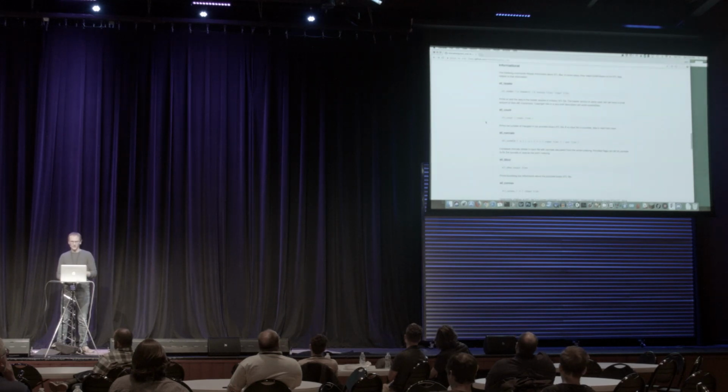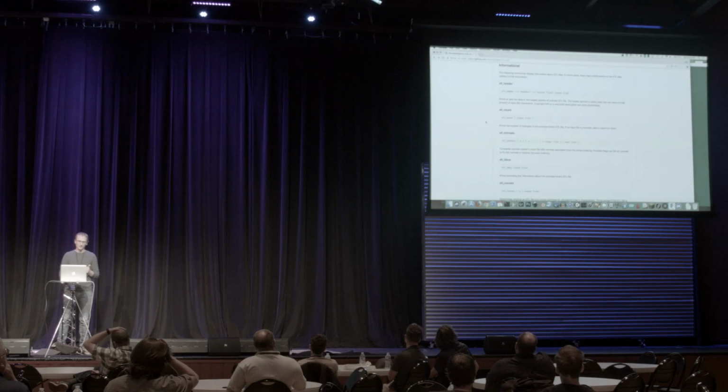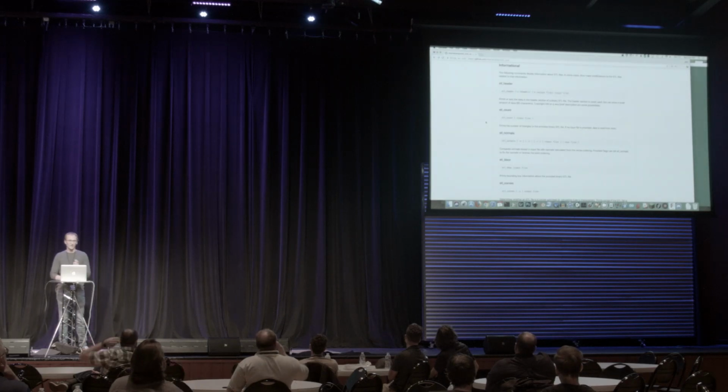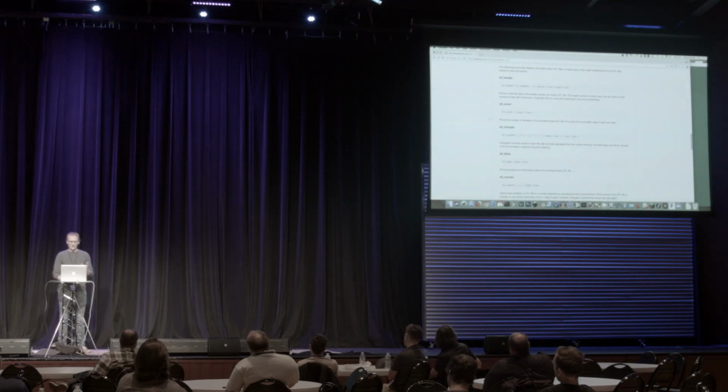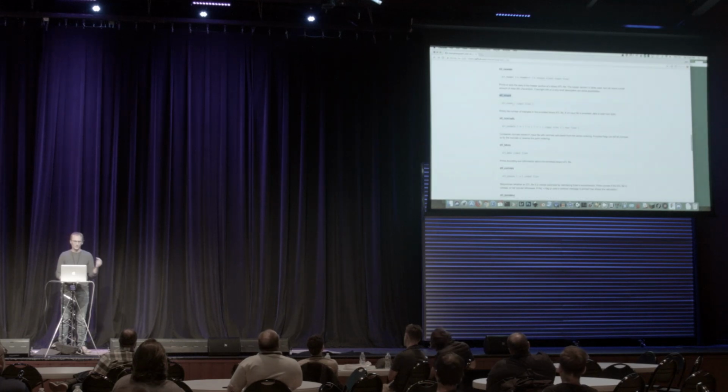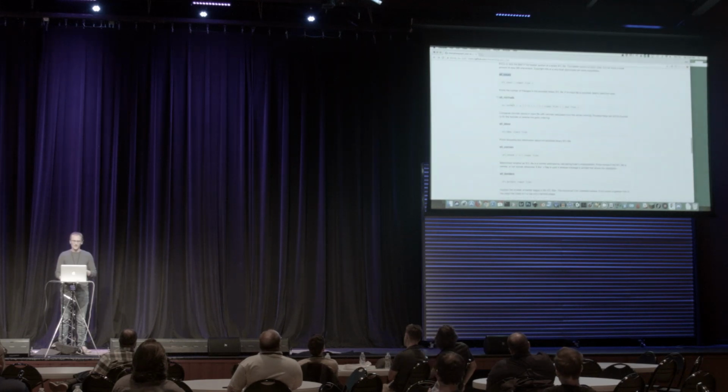But then there's informational STL commands. STL header, we can inspect that 80-byte header at the top. You can also manipulate that. That 80-byte header can be any kind of information. So it's often just a quick little thing like this was generated with this piece of software. So you can look at that. You might also put some copyright information or something, but it can be anything. STL count just looks at that count byte, so it's super quick. It just looks at that and returns it.